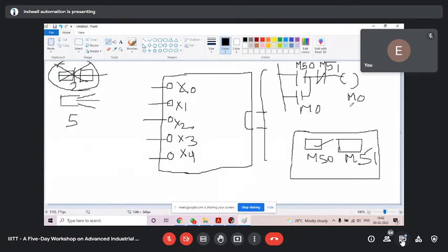Now I shall go to the HMI software, and as we designed visualization, in the same way we work on the HMI screen. In the HMI software, I shall create 2 push button switches, and to those I shall assign M50 and M51. Now the HMI is connected with the PLC. When we press the M50 switch in the HMI, in the PLC M50 will go high. As your circuit is for start, as in the first ladder I have given you here, M50 pressed makes the start signal high, it will latch and your process will start. In the HMI, as you press M51, this will break the latch and the system will stop.